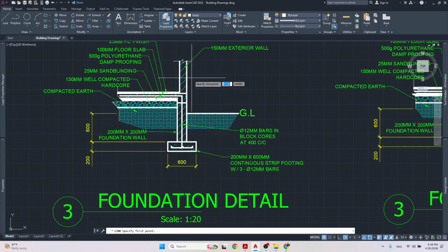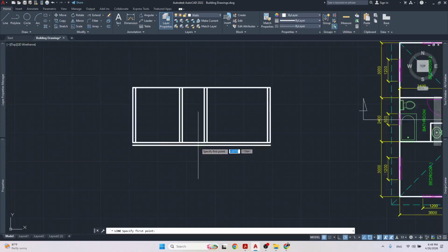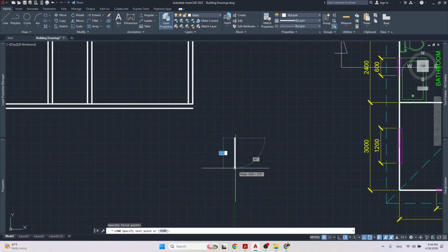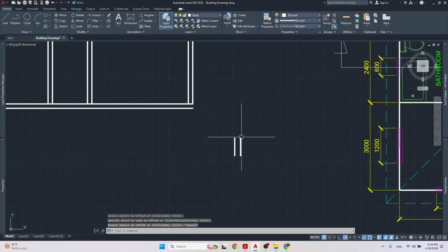But instead of doing the external wall and the footing separately, I'm just going to do the footing and the foundation wall together. So I'm going to draw the foundation wall. I'm going to put this down, let's say 3 feet, 2 feet, sorry, so 600 millimeters, and then I'm going to offset that 200 millimeters because that is the specification they would give you. 8-inch block, 200 millimeters.